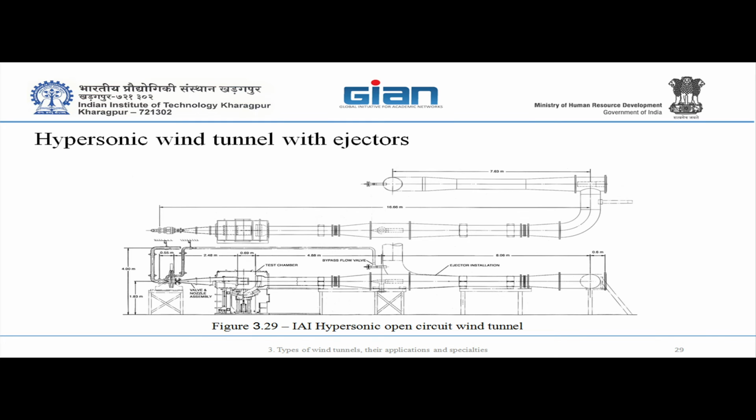Mach 8 and all will be required to cool. You have Mach 12, sir? Yes, we didn't run it. I think we ran it once, but because we were limited in the pressure in the storage, we didn't run it. So what is the T naught, the total temperature, you have? It's something like 750 K. I think I have a graph here for the liquefaction.